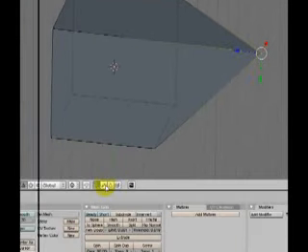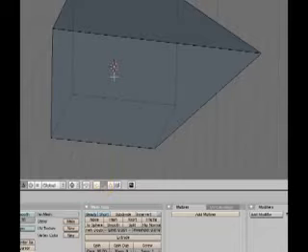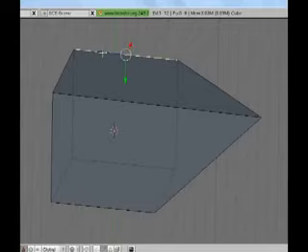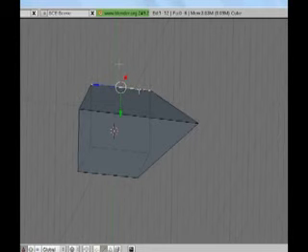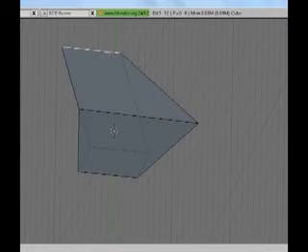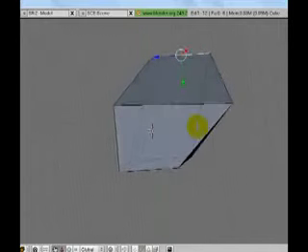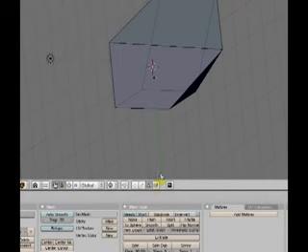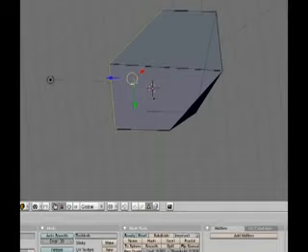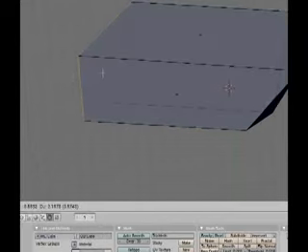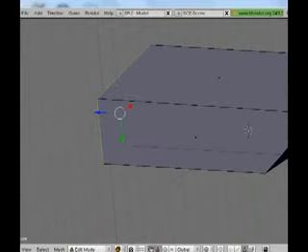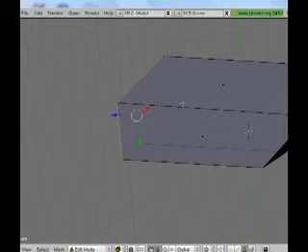So I'm going to go into edge mode, right click on a side, and then I'm going to push G again just to show you the sides moving around and what it does to the shape. We'll pan around. You're getting a pretty funny looking shape now. One more, I'll grab a side, and then I will pull it out. It's going to stretch the whole thing. I'll proportion it to the size of the face. So there you go. That's grabbing, which is what it's called with G.